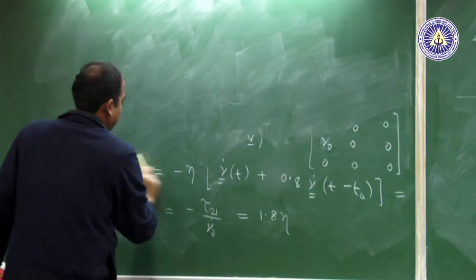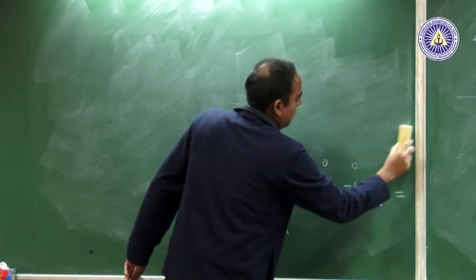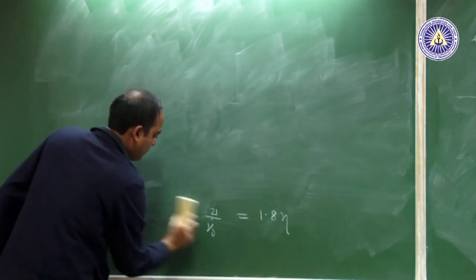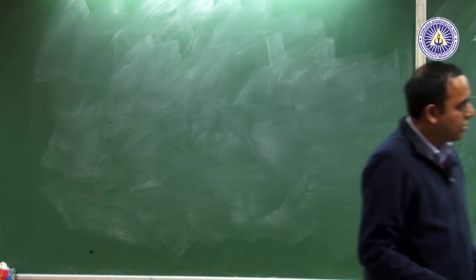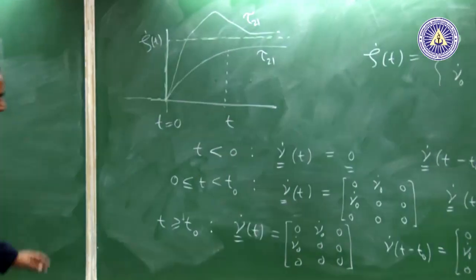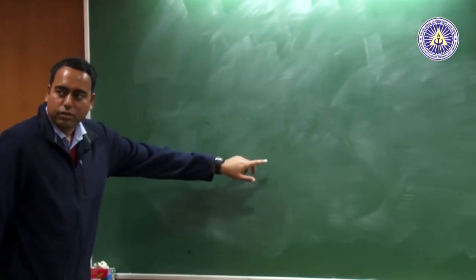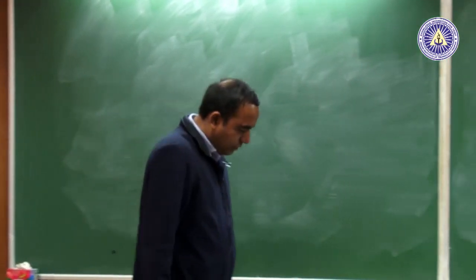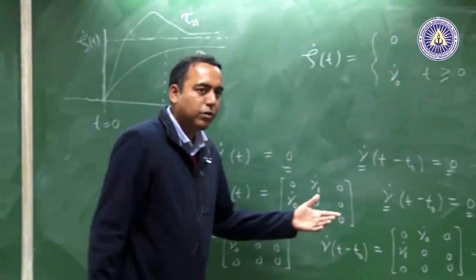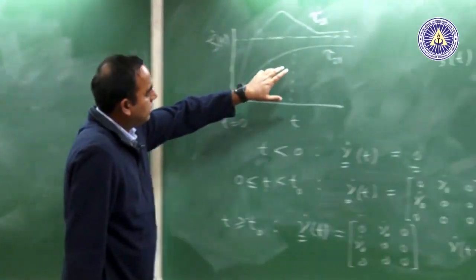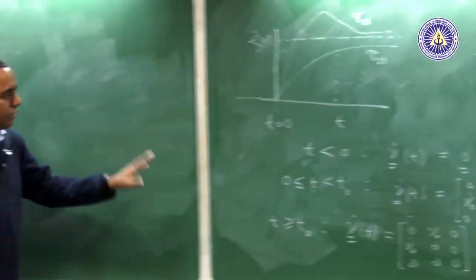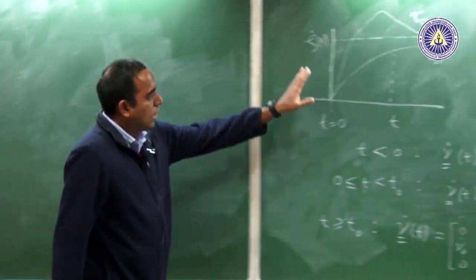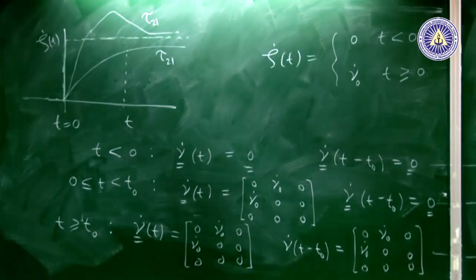Let me highlight what we achieved so far. So, we had steady shear experiments. Steady shear experiments for non-Newtonian fluids show some non-zero values of psi 1 and psi 2, which the generalized Newtonian fluids, which is the first class of models, do not capture. Now, we have the other experiments which are shear stress growth and of course, shear stress decay, which I erased. Again, the generalized Newtonian fluid class of models do not capture these experiments, which involve transients.